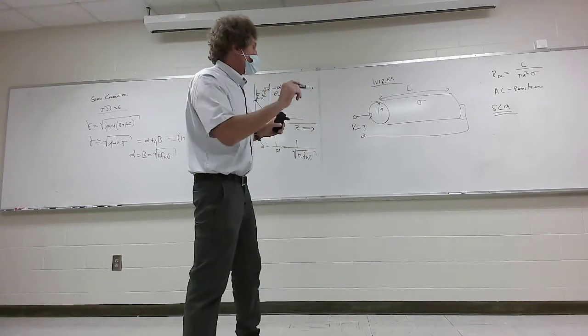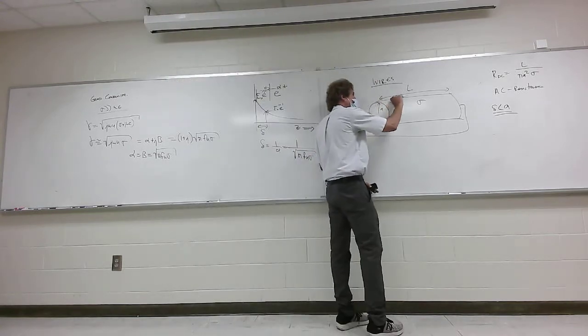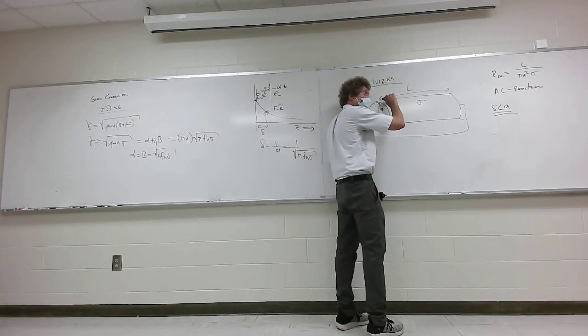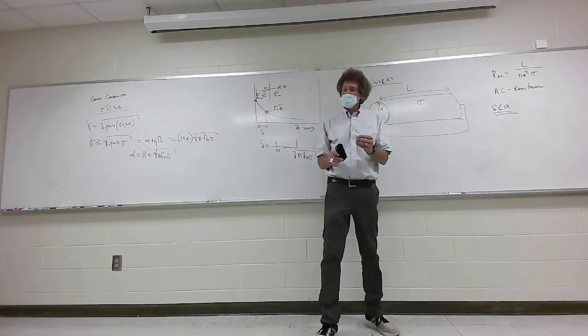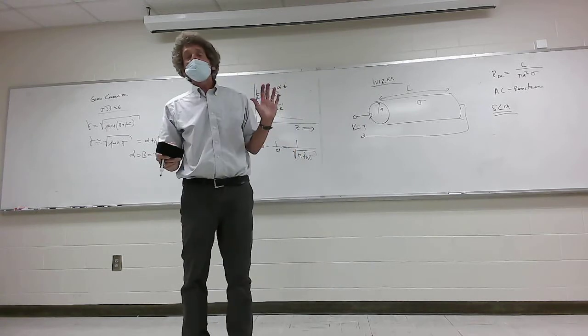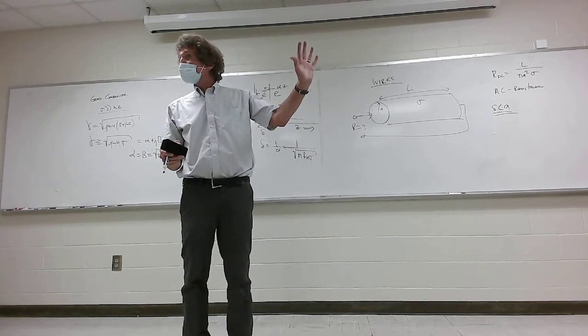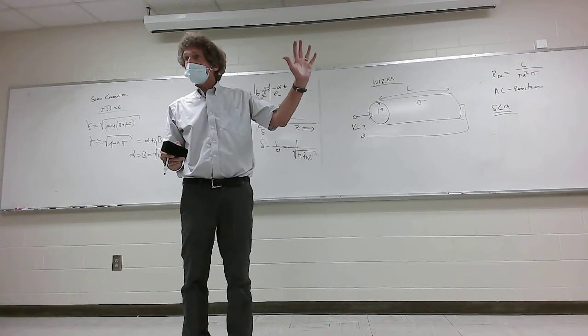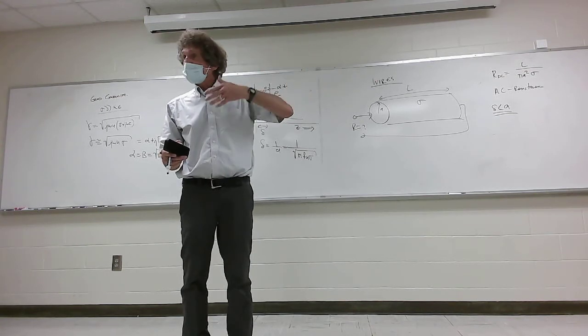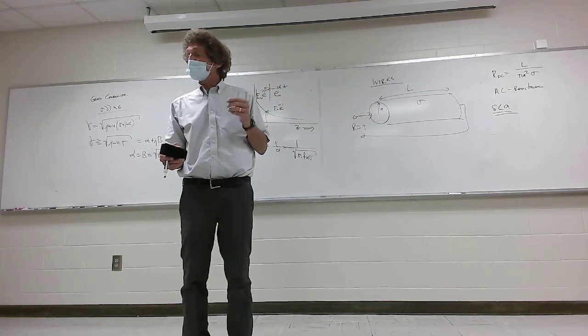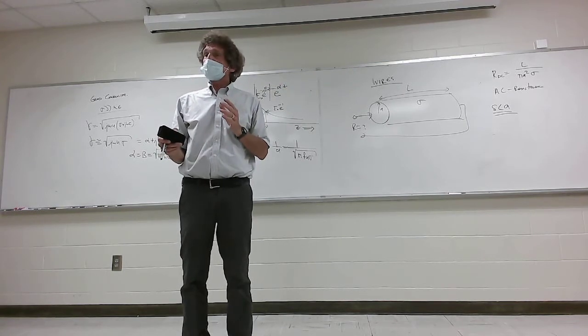If you think about it, when you have current flowing in a wire, you really have this very small, immeasurable electric field on the surface, but this decays into the wire. If you're at DC, it's the same value of the electric field all the way through the cross section. Do you remember when you did your DC problems, you assumed the current, and then you got J equal to what? The current divided by the cross-sectional area, right? And you set that J value equal to sigma E, then you got E and you integrated it and got the voltage and you solved the resistance, right? If you don't remember exactly, just trust me.